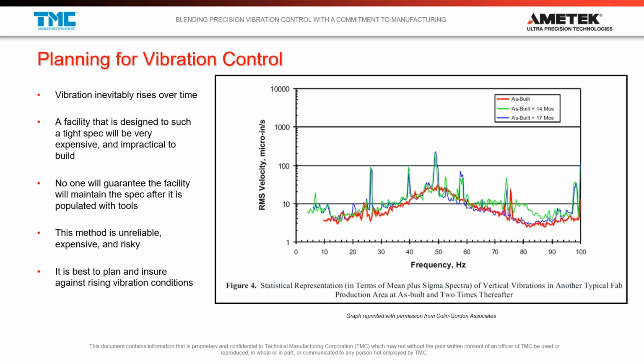And when somebody's going to build a new facility, they might specify the types of equipment that might go in there, and they might say, well, this facility needs to have a certain level of vibration when it's built. And in this case, that is what happened. And you can see here in the red line, after the facility was built, they went there, and it was done by Colin Gordon Associates, and they took a measurement of the floor, and they saw what you would expect of an empty facility.